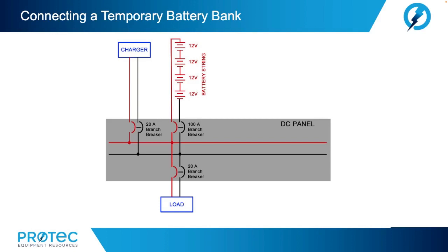During maintenance or replacement of batteries, care should be taken to avoid removing the 125 volt DC from the DC loads. Some sites have DC undervoltage relays that will operate on a loss of control power. Other sites may have relaying that will operate on a loss of communication with the site. If you remove the DC power, you have also removed the protection that those devices provide. If an event were to occur, it would be much more damaging.